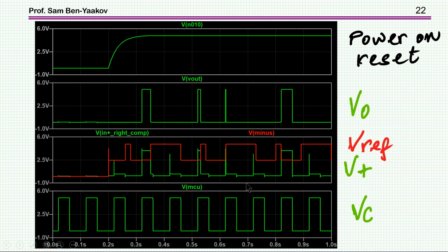And here we see a various situation. We see that we got a pulse coming in, and then very quickly we had a fault. Suppose we connected the switch, current started to flow too high, so the fault goes on, so immediately this goes down. And here we have a case where there was a fault, it was corrected, and afterward we are turning on the switch, and indeed we are getting the output as we should. So this shows how this circuit works in general.